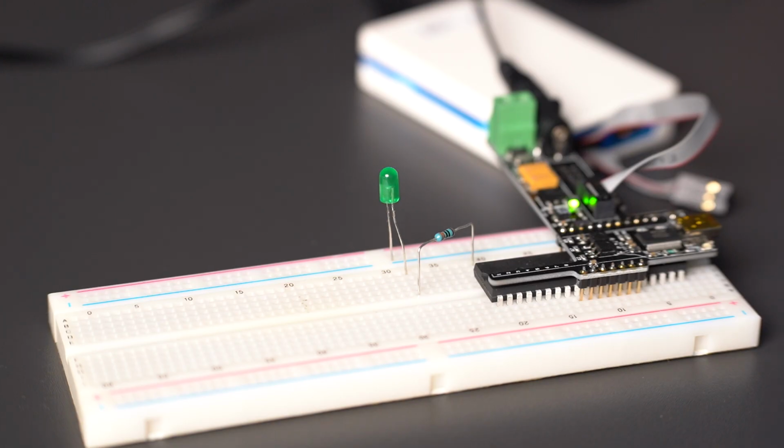It is flashing, but it's not the real thing. Why could this be? As you can see, one period is about 6 to 7 seconds instead of 1. The reason for this is we are not only executing one counter++ instruction, but also a bunch of other instructions. The order of operations looks more like this.